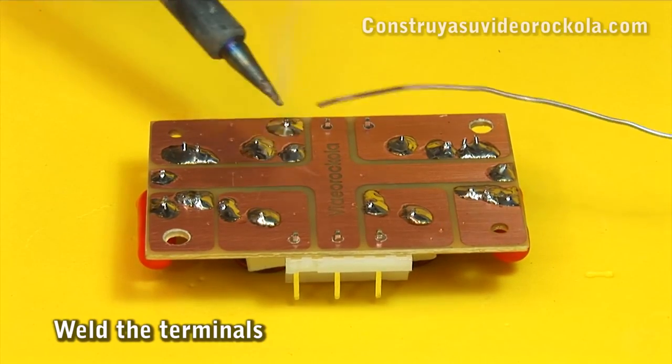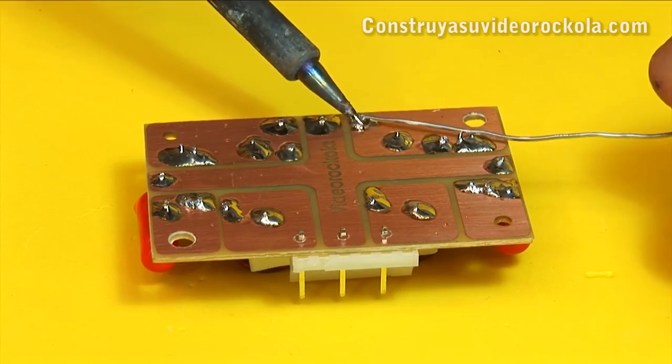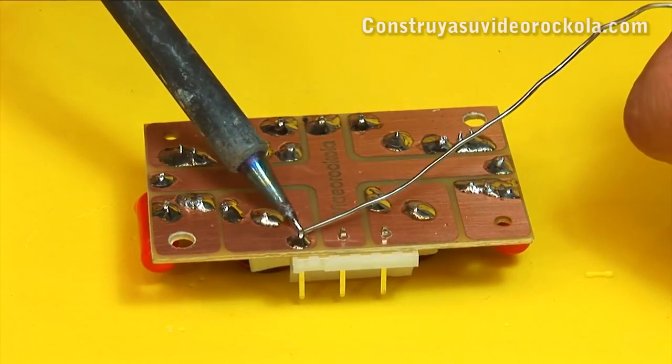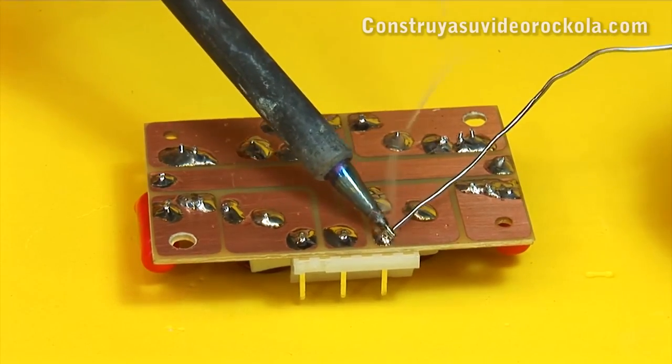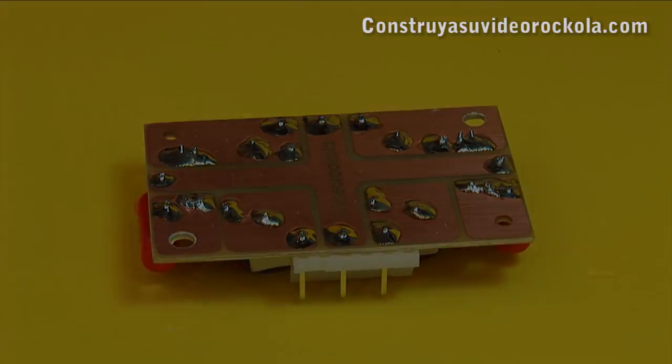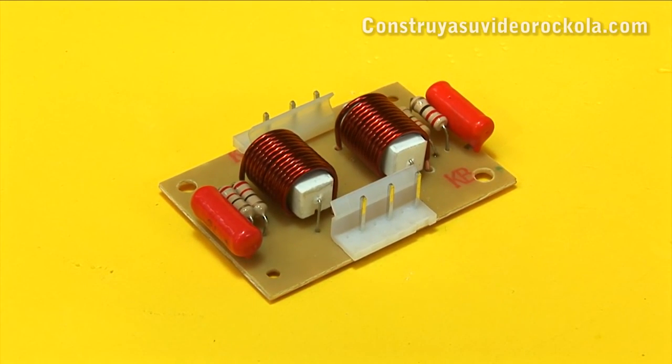Finally, we solder the terminals to the PCB. The soldering should be plentiful, and perfectly surround each pin. We have ready our Zobel network, which we can use with a great variety of amplifiers.